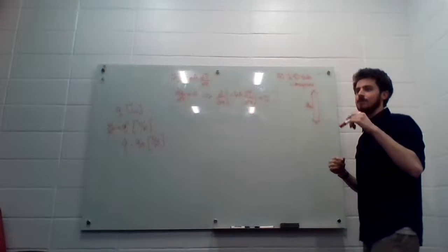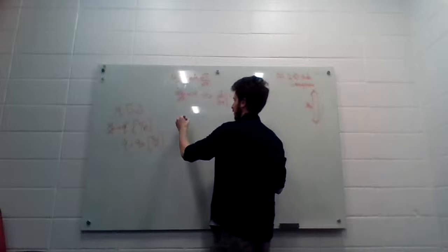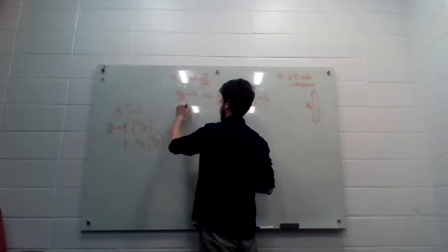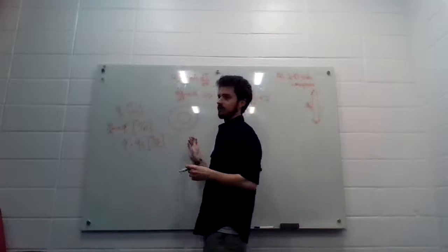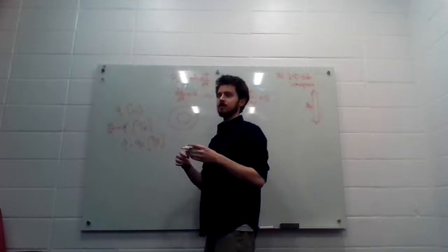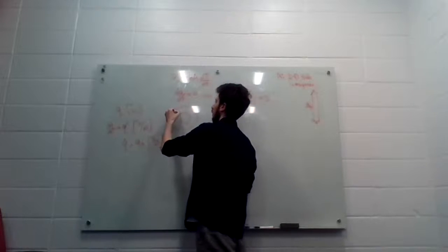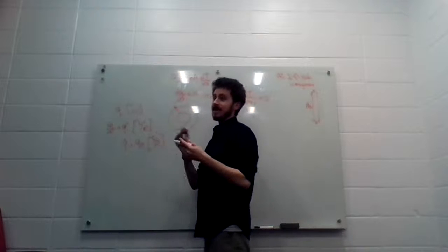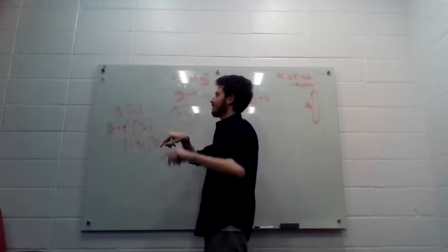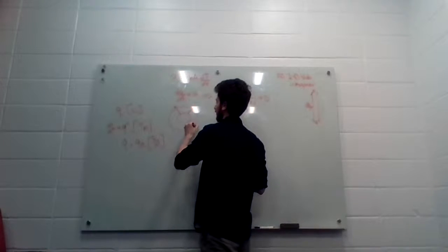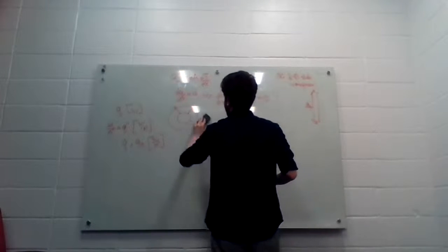Technically, you can have one-dimensional heat transfer through a cylinder. An aside, we'll be dealing with this a little bit later. So we did all that nutty stuff with cylindrical coordinates. Most cylinder problems you'll be dealing with are, say you've got a fluid flowing in a pipe, it's warm inside the pipe, it's cold outside the pipe, you want to know how much heat is leaving, and in that case, all the heat transfer is radial. So it's only going in one direction according to your coordinate system, even though we know it's actually going in 360 degrees. We'll deal with that later. Okay.